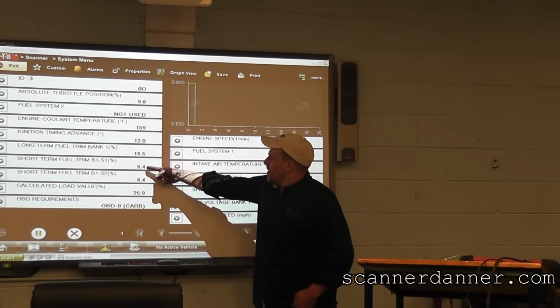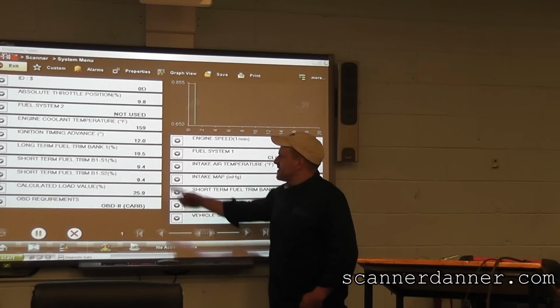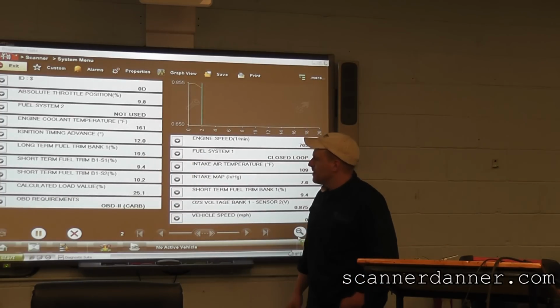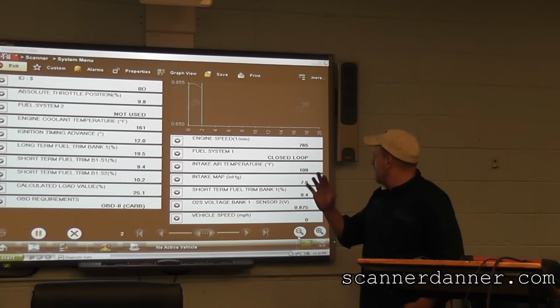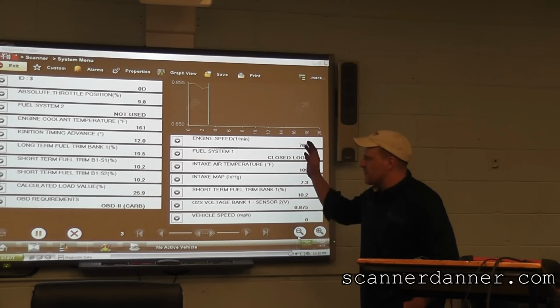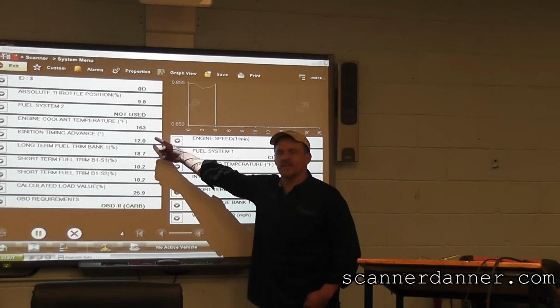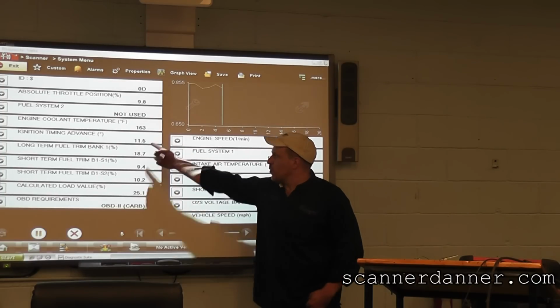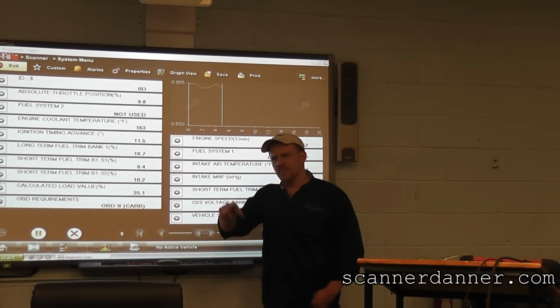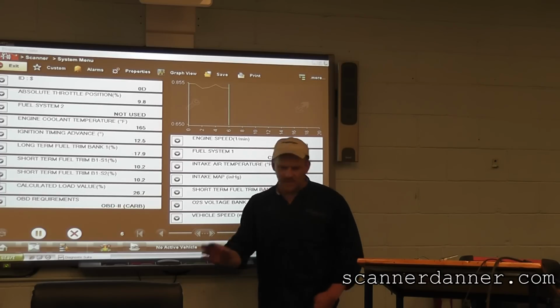Where's my short term? Positive 10, long term still minus 19. Is that going to come down? Yep. Now, the characteristics of when that does that are different for every car, but let's keep watching it. Should counter. Yeah, timing advance. So it wasn't cam. You mentioned a cam. Yeah, I misread it. No, that's okay.